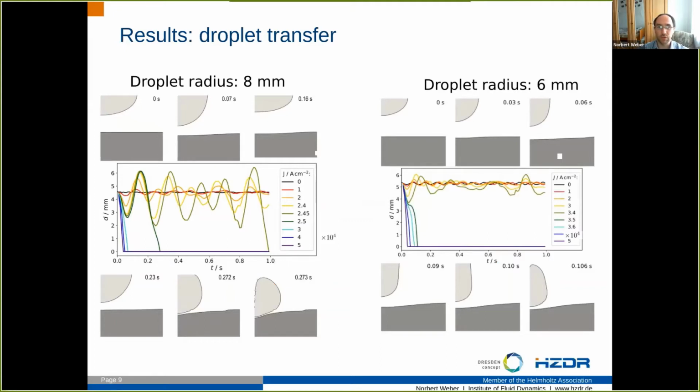Here, I would like to present some results which we obtained. Everything done here was axisymmetric. The metal foam on the top is not illustrated. In some light gray, you see the droplet, how it behaves over time. On the left-hand side, this was really a large droplet. We first initialized it and switched on the gravity only, so that it gets a steady shape, and then we additionally switched on the Lorentz force, or the current basically.